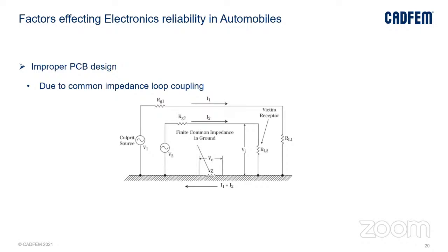So a voltage can be induced, and this can couple with the nearby mesh. This could act like a radiator, and this loop can be a victim, and the current inside this loop may change.